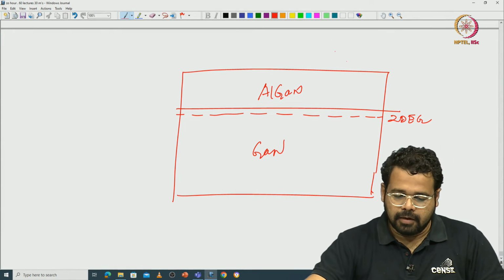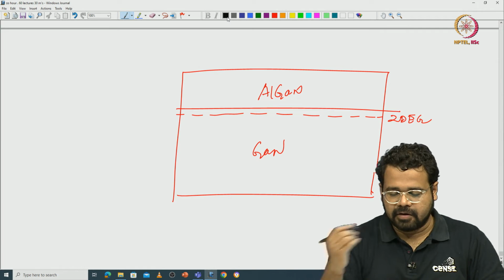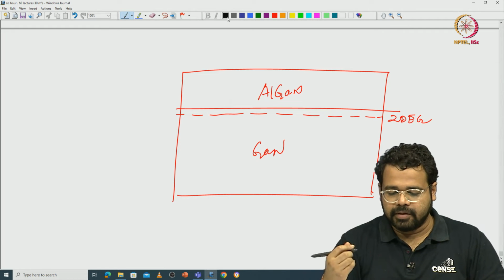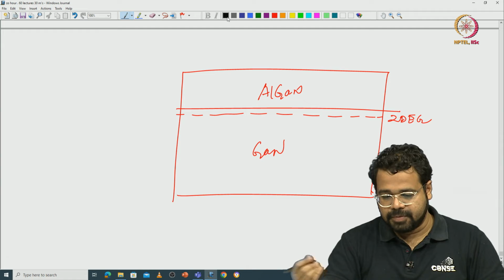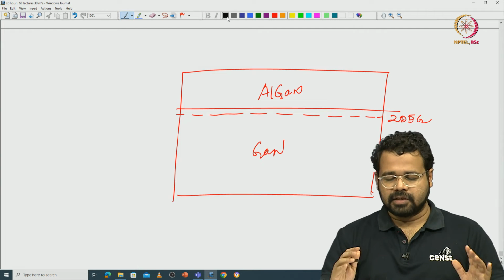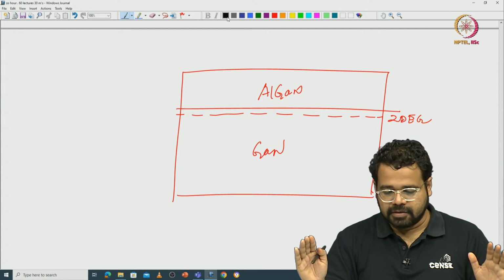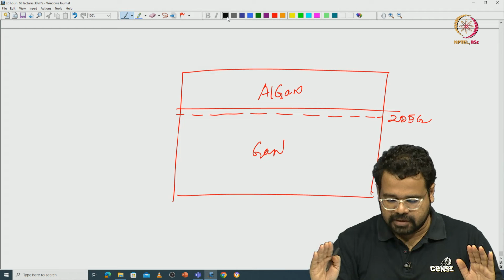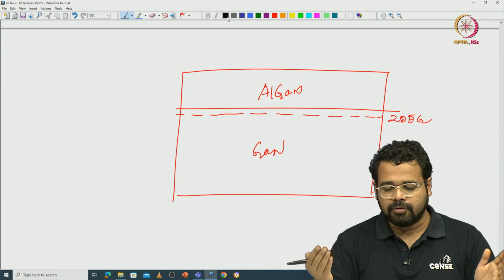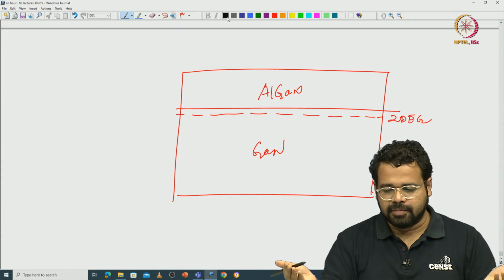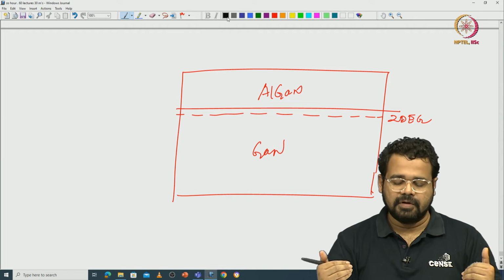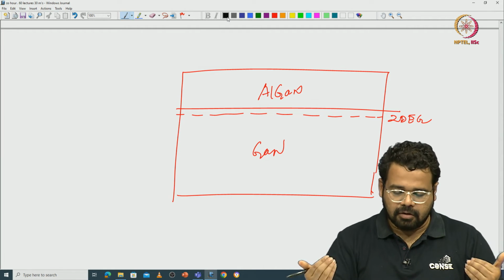Of course, we have discussed field effect transistors in great detail when we discussed GaAs HEMT, MOSFET, and indium phosphide based p-HEMT. We have had a generic discussion on field effect transistors, microwave field effect transistors, not just any field effect transistor. We discussed many key concepts of field plates, gate recess, ohmic contact, etc., but we will discuss them here in the context of gallium nitride HEMTs, okay.